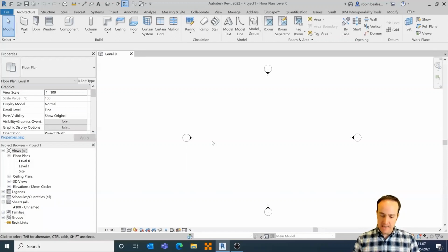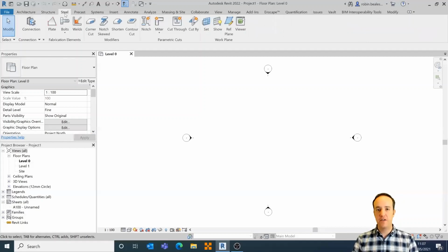So I'm inside of the system now, and essentially what I have is three or four main areas of the interface. So firstly, on the top, I've got my toolbar, which is called the ribbon. The ribbon is intuitively split up into several different tabs for different areas of the application. I'm using full Revit today, so I've got the full suite of architecture, structure, and systems-based tools. Obviously, Revit LT only has the architectural-based tools. But things are really easy to find, and actually it's set up very similarly with the same kind of icons that you're used to seeing inside of AutoCAD, for example. So you'll see that as we go throughout this demonstration.